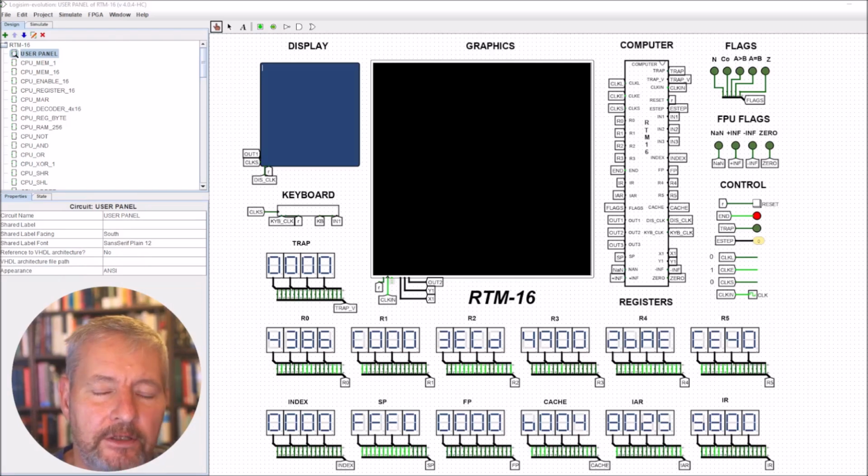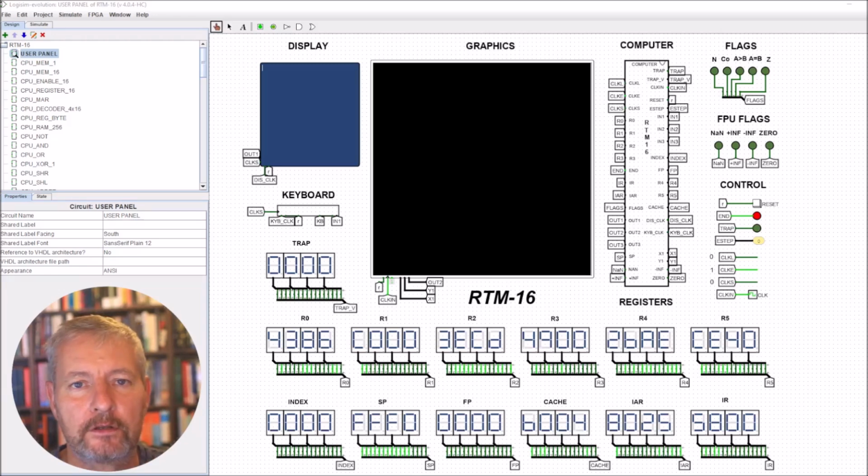So this video has given you a flavour of how to run some code to test the floating point unit, and also once it's been tested to take the values and check and see how accurate they are. Now you'll notice when I mentioned the division and square root, we've generated those using the fast inverse square root algorithm.